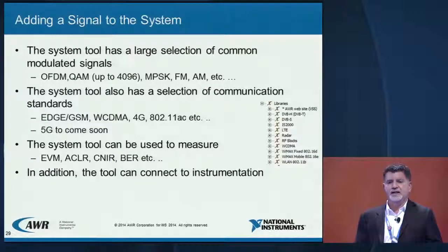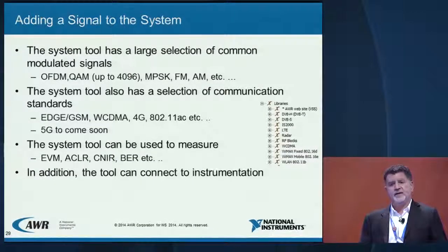Now we move on to the next step. I made all my qualifications for spur analysis. My noise figure analysis is done. I could utilize VSS signals to stimulate the same link. And at this point, the metric is going to be different. The metric that we're going to be looking at is bit error rate.